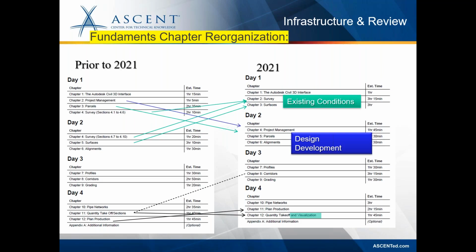So that is where we get into taking the multi-view blocks, for example, the building footprints and the trees and some light standards, and we plop those into our Civil 3D surface and have them raised from the existing to the finished ground. So it's a lot of, I think it's a lot of fun, and it provides the students a positive note to culminate the 4 days with.